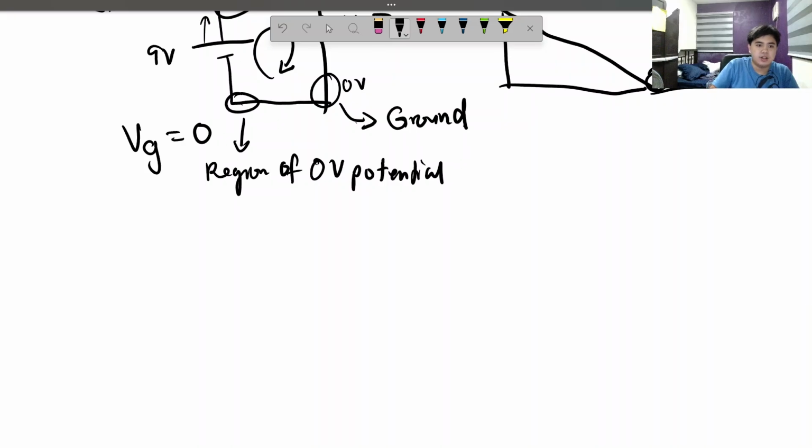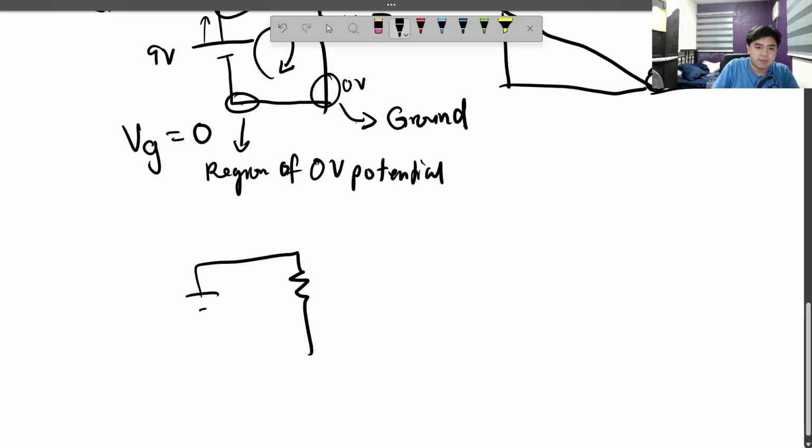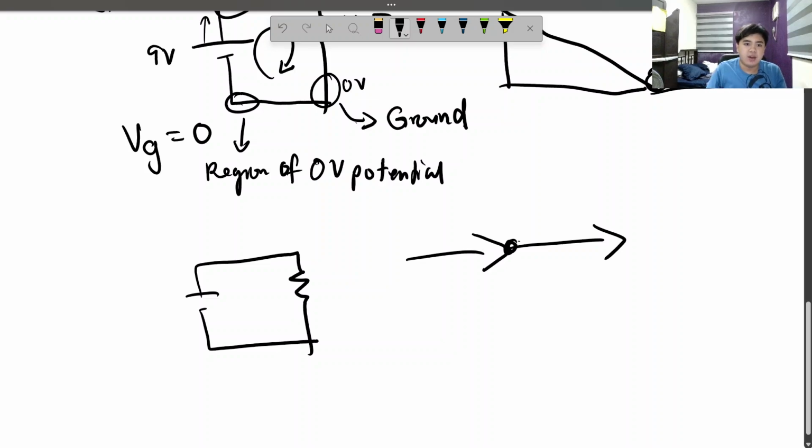What about Kirchhoff's current law? So, for example, another circuit here, same parameters. The only junctions that exist in this is essentially this, right? Current goes in and current goes out. There's no triple in here, so no additional current goes out or in. So this is just going in and going out. This means that the current going in must be equal to the current going out. So within the circuit, the current in a series circuit must be equal to itself.